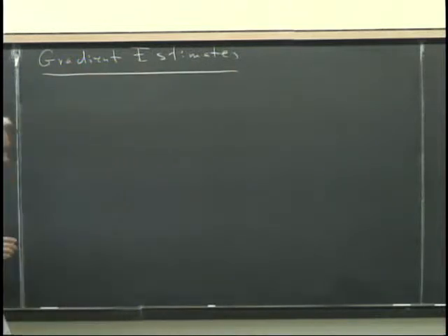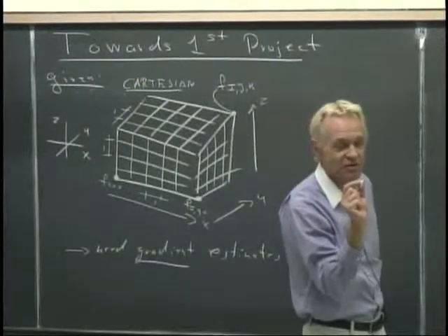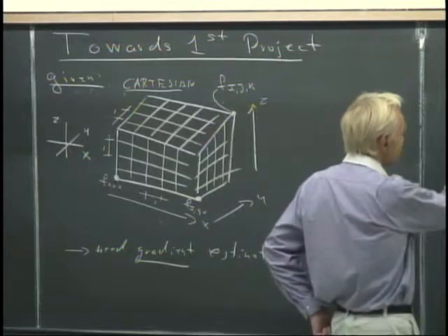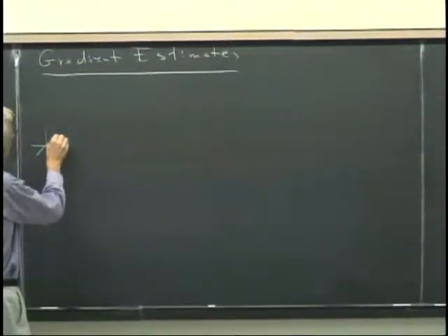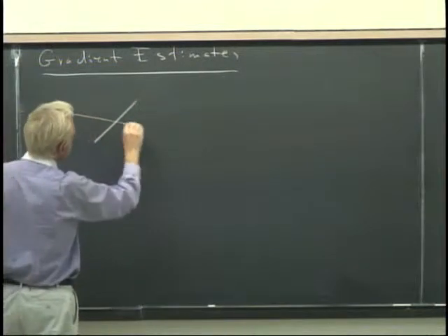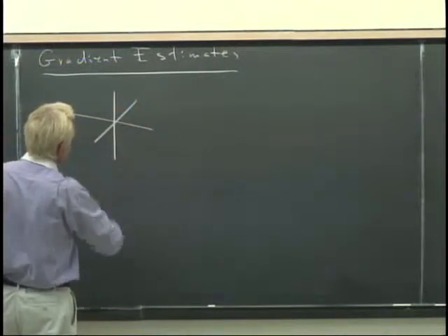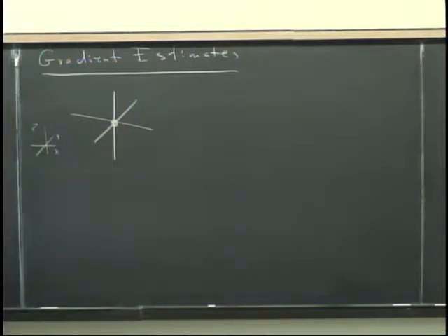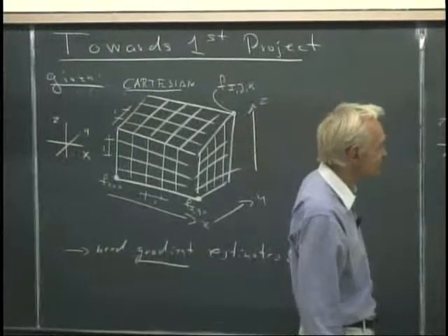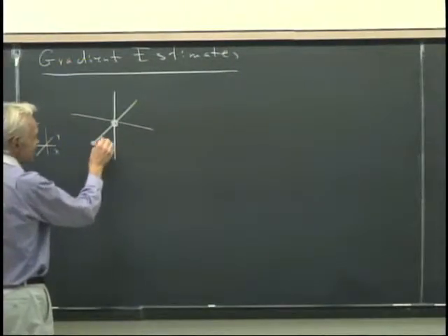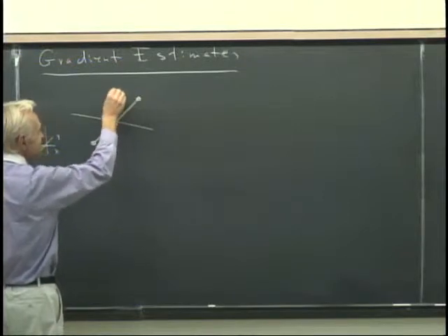Again, we only need to understand how to obtain the gradient at one of these locations, one of those points. If we know how to do it for one point, we know how to do it for all the other points. So in XYZ space, we have this configuration. We have a particular location ijk in terms of index, but ijk is also the coordinate of that point because we are Cartesian. And this guy has 6 neighbors in this Cartesian mesh.